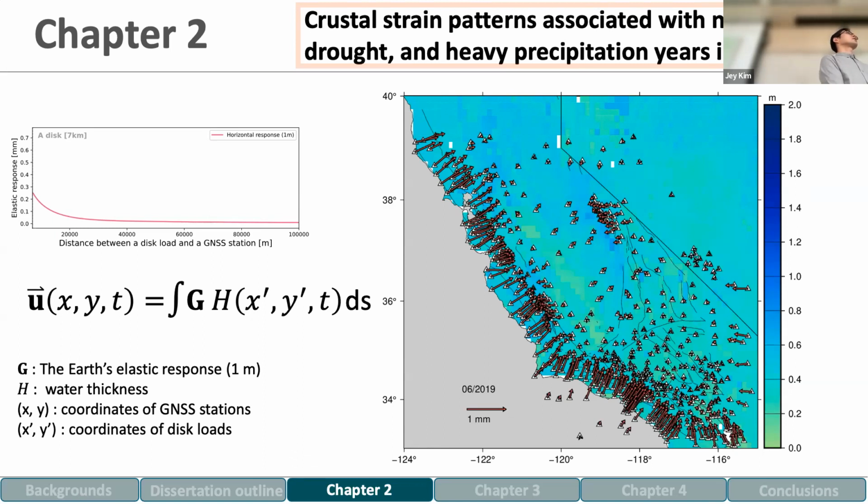And to justify that, before I use GPS data, I analyze vertical time series. If you see the vertical response, then you can roughly say whether the station is affected by poroelastic or elastic response. If it's affected by elastic, when you add water, you should expect subsidence. When you lose water, you should expect uplift, right?